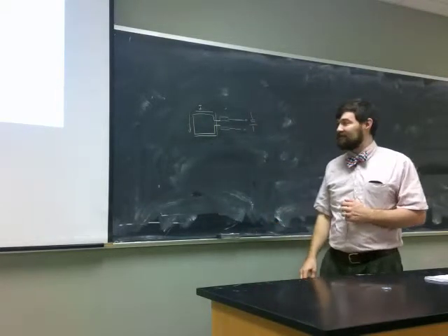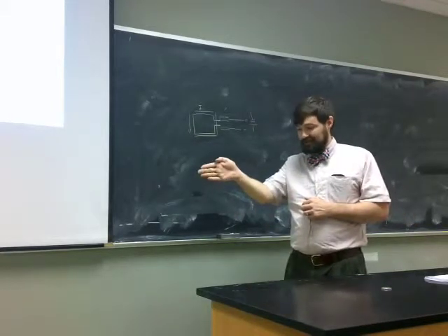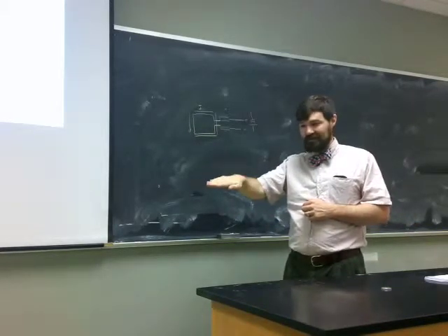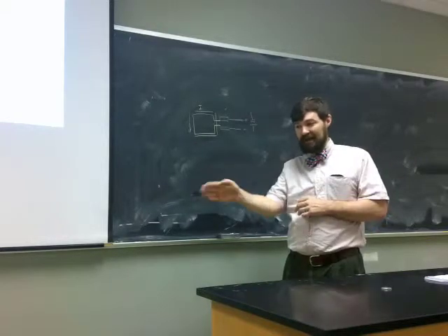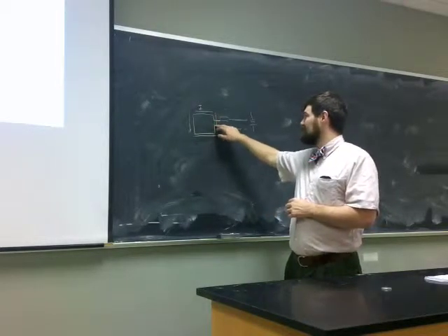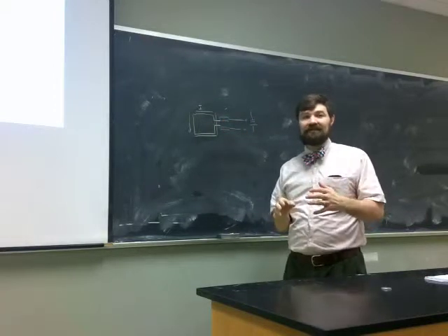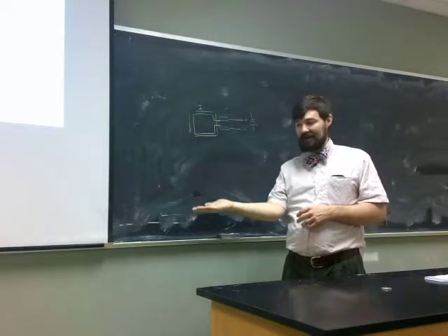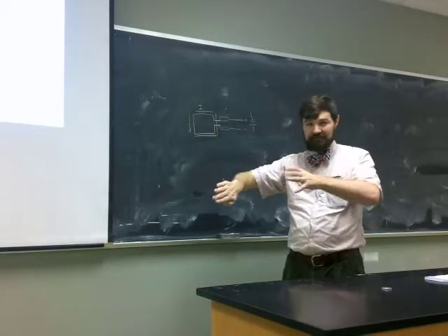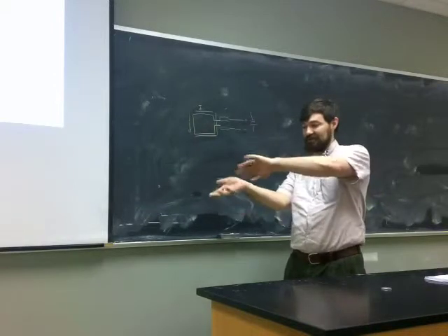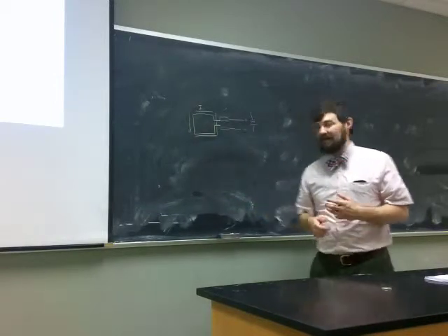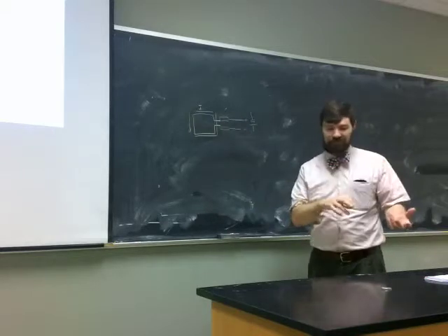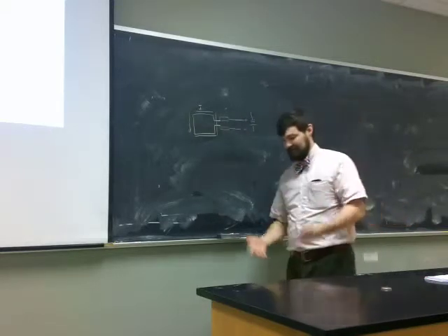Okay, what that does is it ensures that when the loop flips to here and should otherwise stop and go back, the two leads flip which side of the battery they're connected to. And so instead of flipping to here and stopping and then flipping back, you flip to here and now you've flipped contacts, and that means that you get an additional torque, so it just keeps spinning. During some parts of the spin you have more torque and some parts you have less torque. But you always have torque in the same direction, so it spins and spins and spins.